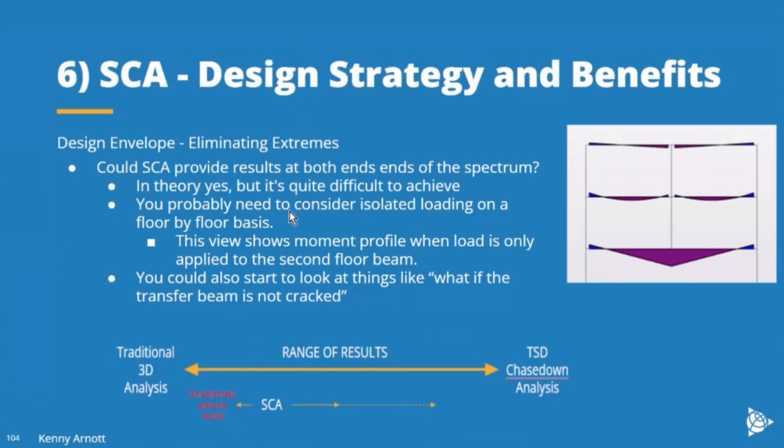Another question that people could ask is, could the stage construction analysis be used to emulate the sort of results you expect in these beams at another level? In theory, yes, but it's quite difficult to achieve. You probably need to consider isolated loading on a floor-by-floor basis to achieve something approaching that.